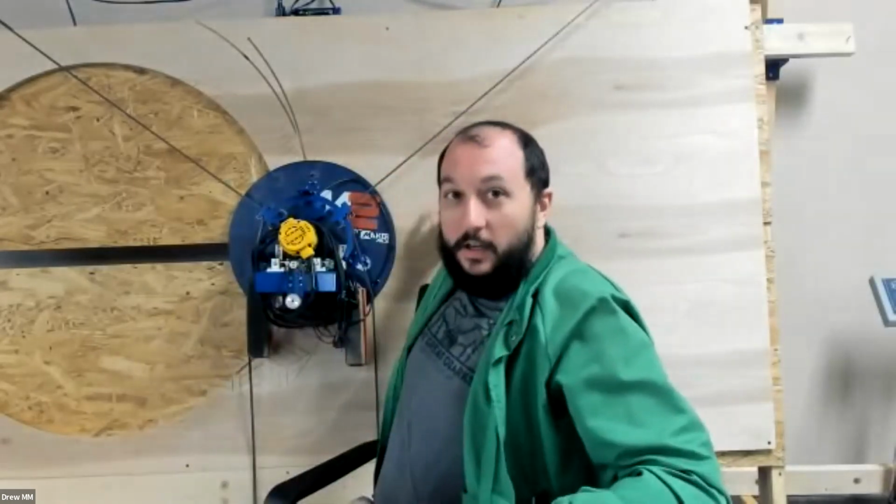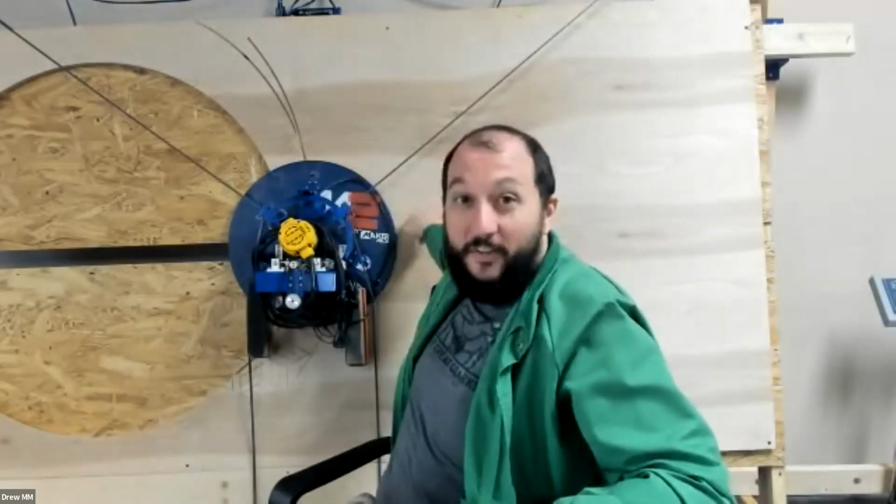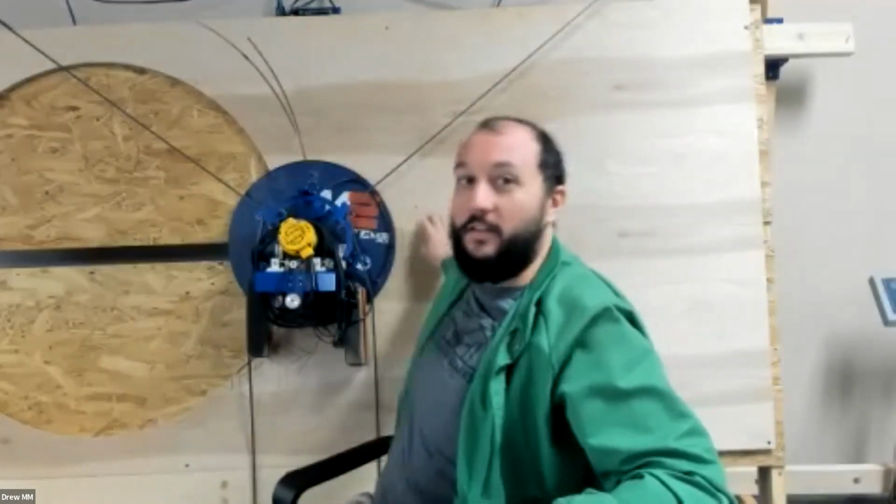What's the difference between a down cut and an up cut? So, in the different bits. Okay, I understand one is going to pull up and the other one pull down. Right, yeah, exactly. But in terms of cut, it's all about precision. It's all about what side of your material you want to look better. So let's say you want this side to look better, then you'll do the down cut, because this is going to be your facing side. Like your material, this would be the front of your sign, for instance. And then your chip out and the blowout would be on the other end. And then it's the opposite for the upcut. So if you wanted the other side to be smooth, then you would use the upcut and your chip out would be on the top.